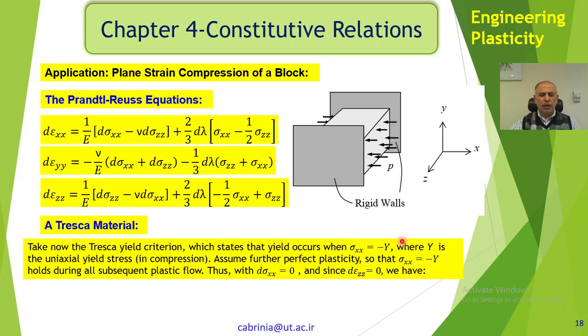Okay, I should mention that here we have assumed an elastic, perfectly plastic material. But if after yielding the stress increases, that means the material is strain hardening, work hardening, and we could use a proper work hardening model for that. Now, we are not doing that here. We are just using the yield condition and this number alone. So we don't have any strain hardening.